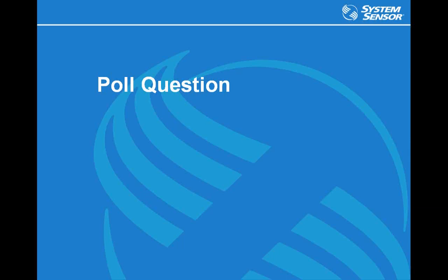Okay, a follow-up question on measurement of the dB with the test tone. The attendee wants us to confirm that that's done in the field, and is there a specific dB that it should be tested at using a microphone? No. Whatever your ambient noise is in the space that you are measuring intelligibility, your dB level with the test tone should be 15 dB above your ambient, and that's where you would run your intelligibility test. So I hope that answers the question.